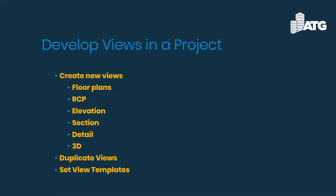So a user would have to go in and create a dependent view, and you actually create multiples of these, and you go in and crop down to the area that you want to show for each of these dependent views. And you go in and place those views on different sheets. You have a decent scale that is viewable.